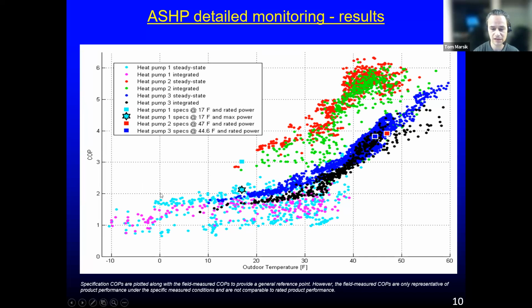So if you can run a heat pump with a COP greater than about 2, you are saving money when you look at the cost of electricity for the heat pump versus the cost of heating oil that you would be using for heating. So I'm pointing all this out, because we have a lot of people from Fairbanks here, to point out that with some of the newer, most efficient heat pumps, you can operate them down to roughly 0 degrees Fahrenheit in a beneficial way in Fairbanks.